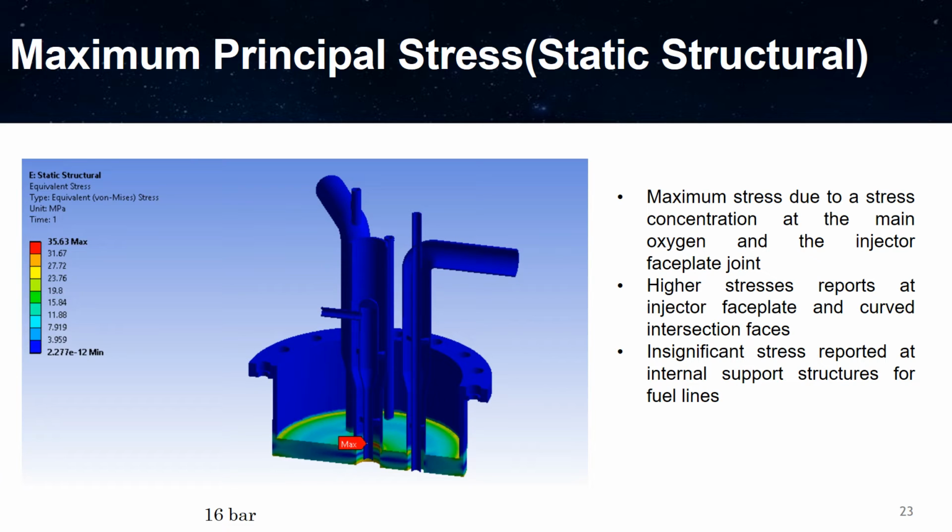If you look into the stress case, you can see the stress is reasonably resolved all over the injector, except the injector face. The stress is reasonably lower everywhere else. On the injector face, the average stress is around 15 megapascal, and around the edge of the injector, the stresses are around 20 megapascal.